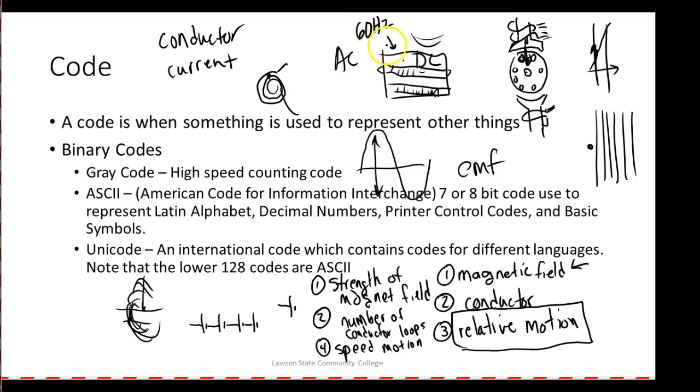So as the speed of the rotor comes up, the difference in frequency goes down and you induce less voltage into the rotor, which creates less torque. But when do you need the most torque out of a motor? When you start it. So whether you understand that precisely, you'll learn more about it, especially if you take the motors class. But this is why AC motors are so cheap, because the rotor itself is nothing but a big chunk of metal and big solid conductors running through there, right? You understand that?